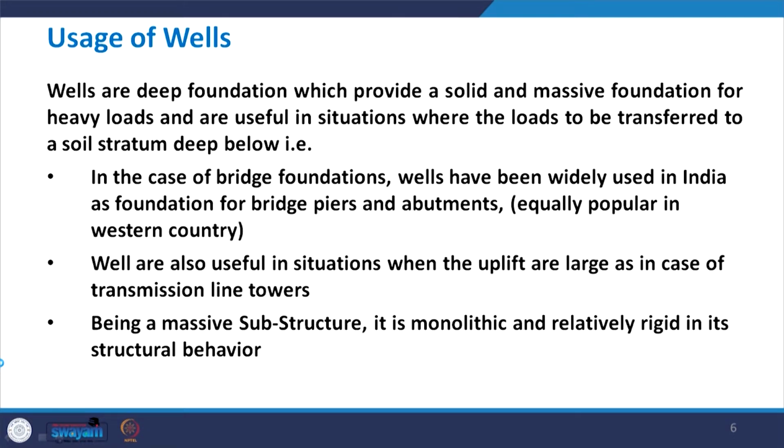Wells are also useful in situations when the uplift is large, as in the case of transmission line towers. That means, when due to wind forces or some other reason there could be uprooting of the towers, it can generate uplift, and in that case also the well will be useful.